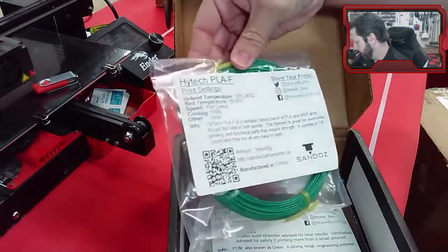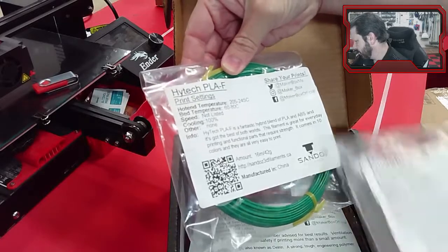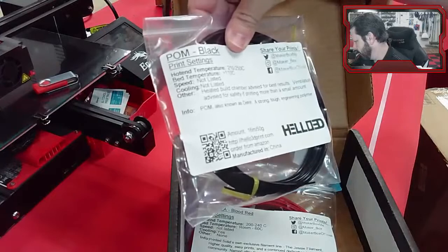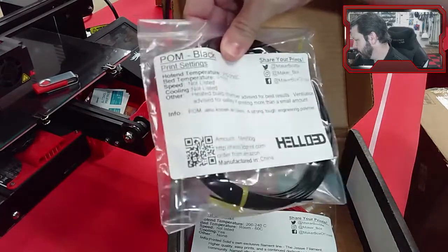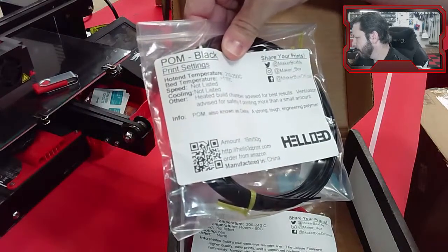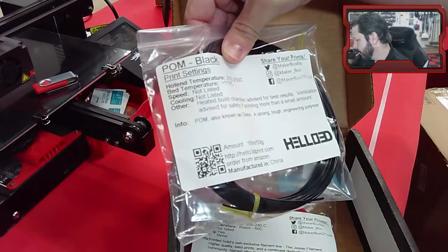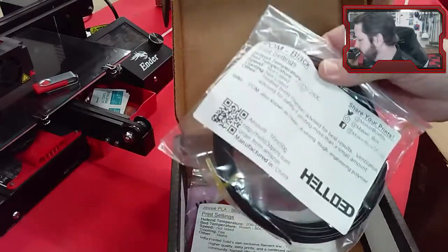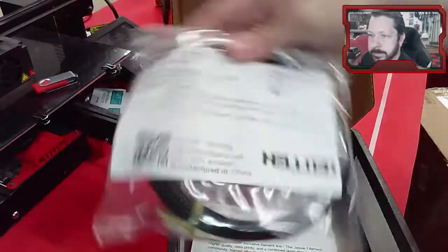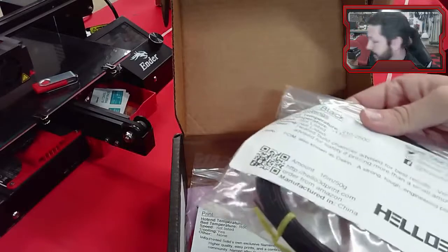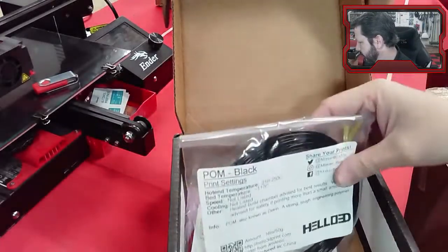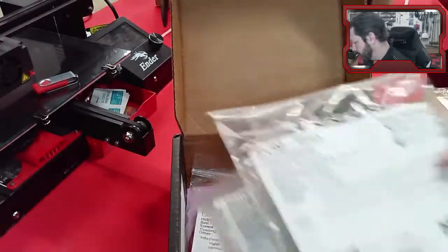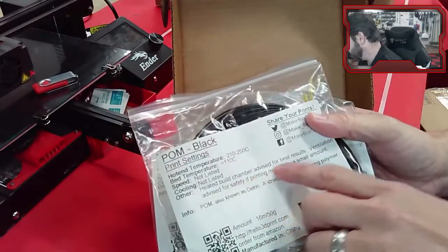Here's a different PLA. It's a mix of PLA and ABS. Here's a Delrin. So this one we probably won't be able to print on our stock Ender, but later at the end of the quarter we're going to change out our print nozzle and actually the whole print head so that we can print higher temperature stuff. This also needs a chamber, so you might see heated build chamber is advised.